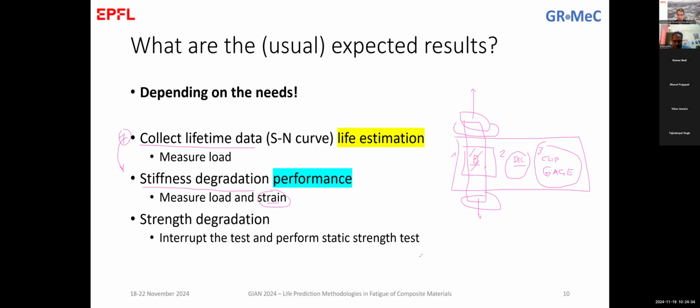There is another method that is used. Physical measurement of a broken sample? No, because this is correct, but this does not give you also the evolution of the strain during the loading. And also what you miss with this is that at the end, when the sample fails, it might recover. You test the sample, you load it, and then when it fails, it goes back. So you don't have the total strain when the specimen is broken.